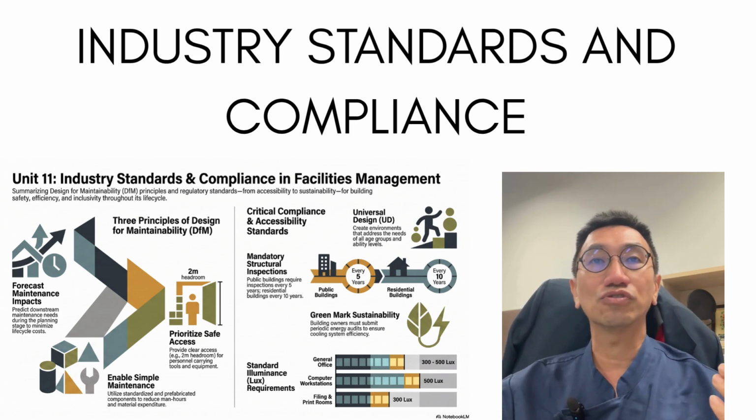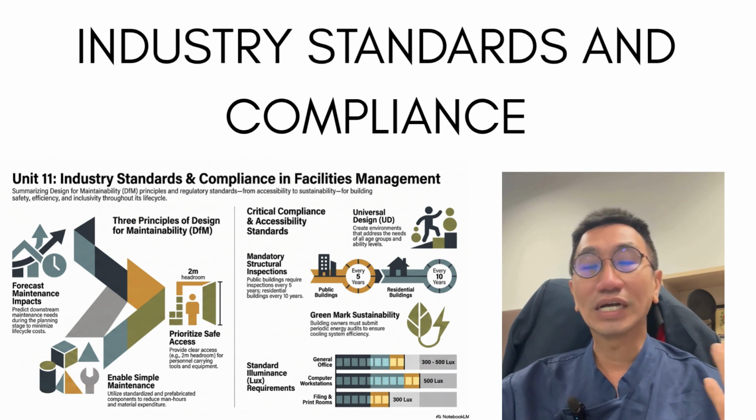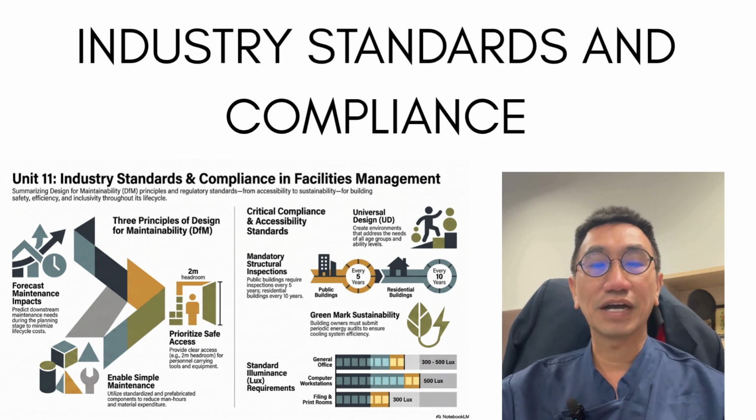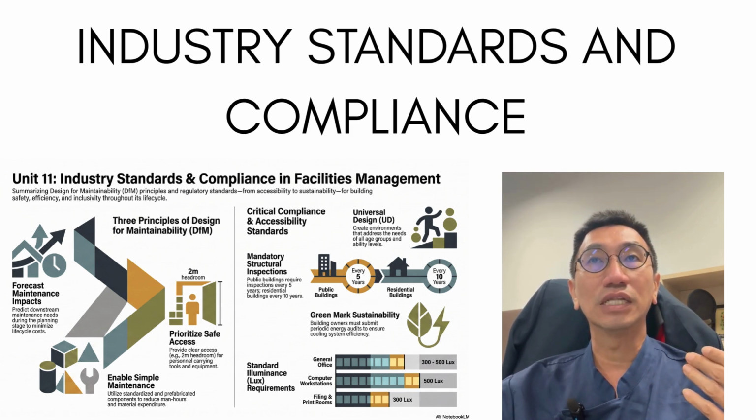Noise in the office should be about 45 decibels, okay, and then for worker safety, the sound pressure should be not more than 85 decibels for an 8-hour workday without hearing protection. So this is basically what we are going to learn on the standards side.